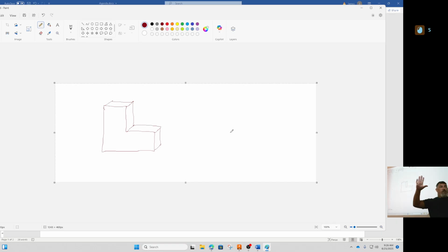So it's kind of the easiest one. You just do the front view, and then you do lines at an angle for your depth, and just make them all the same length. Does the angle matter? Yes. What about the angle matters? The degree. Does it matter exactly what degree that is? They have to match, right?